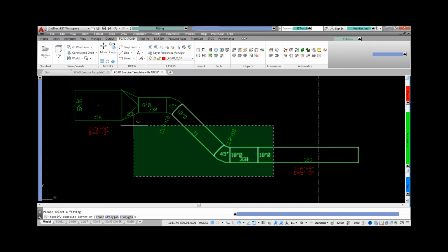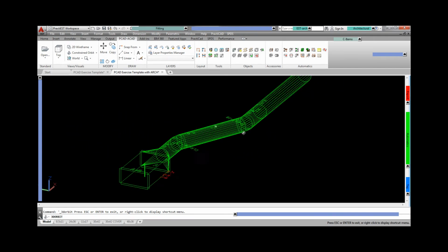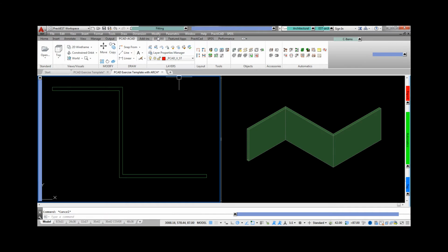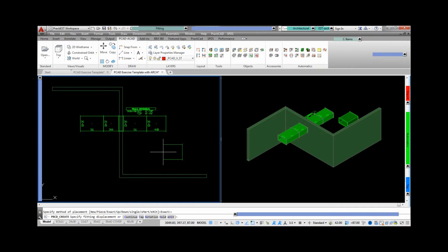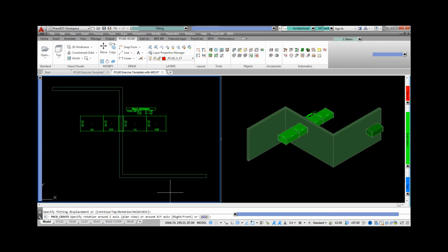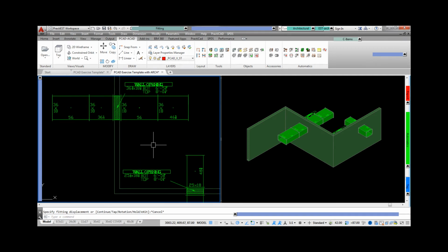Use AutoRouting in conjunction with PractiEst and you can see which of these scenarios is the most cost effective for your shop. But the routing options don't stop there. We can create damper routes to automate the placement of a damper inside a fire rated wall. Just grab a piece of duct, route through the wall. You can have the damper you want selected, positioned, the wall opening created, and the proper tagging to show your heights and opening size. This can greatly aid you in producing a fast wall opening drawing.